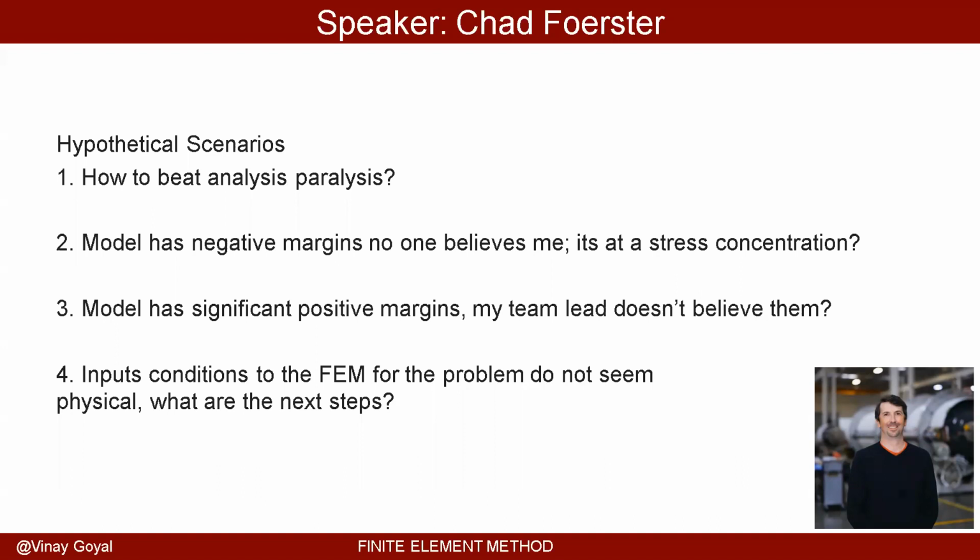That's what I focus on first with negative margins: look at the elements. If it's maybe 3 or 4 problem elements, maybe in a feature like Vinay's talking about, expand out by a factor of maybe 5 to 10x, take those elements and really look at them and ask, is there something weird going on here? Is it not attached? Sometimes you get nodes that are not attached and it's very imperceptible. And so you get splits, almost like seams in models, especially shell models. And it's just an artifact of getting a model from someone else and not checking it.